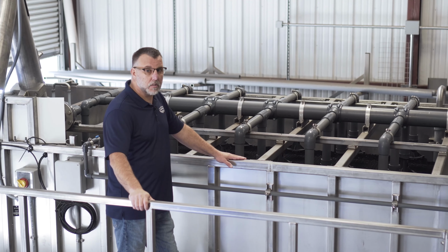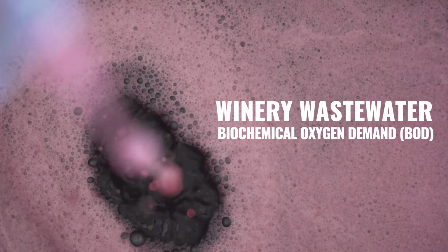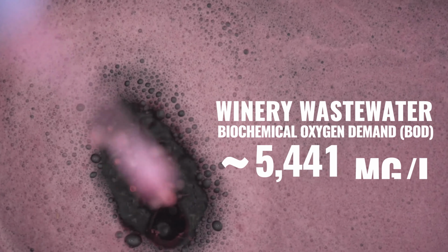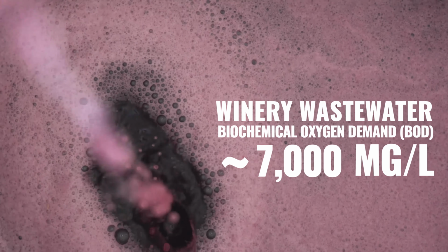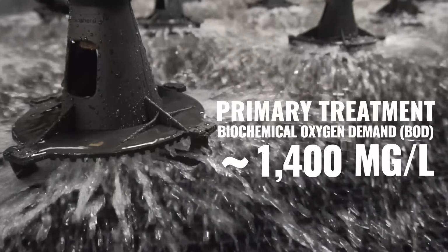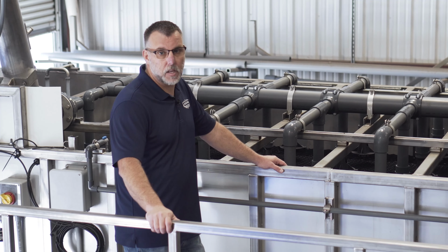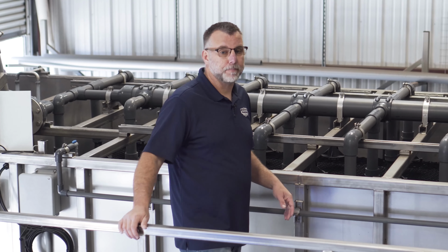The primary system is to remove the bulk of the BOD. Winery wastewater can have a BOD on average of 7,000 milligrams per liter. We're trying to reduce that by as much as 80% in the primary treatment to improve the quality of our secondary process and reduce sludge production.